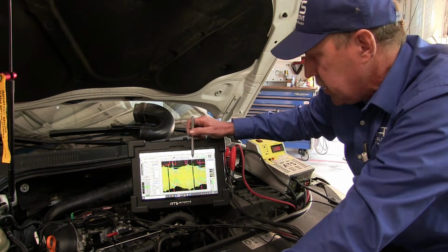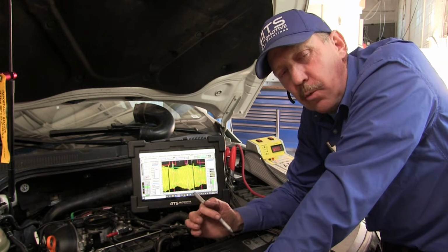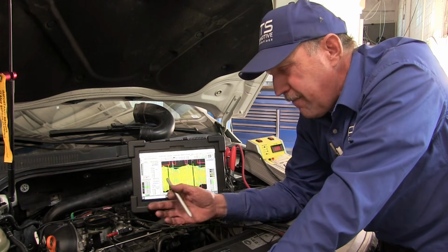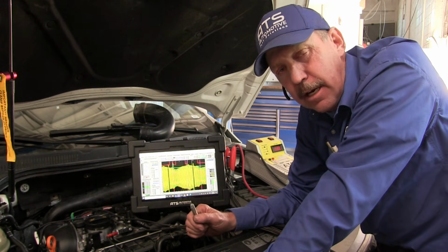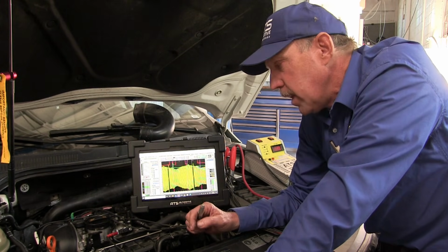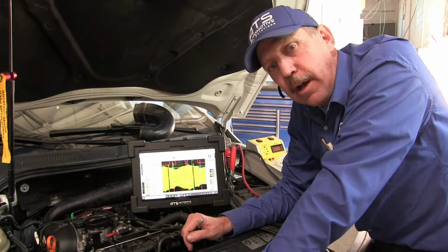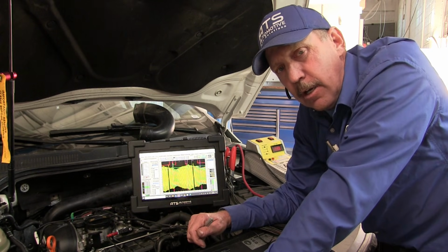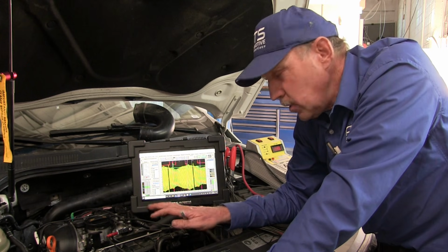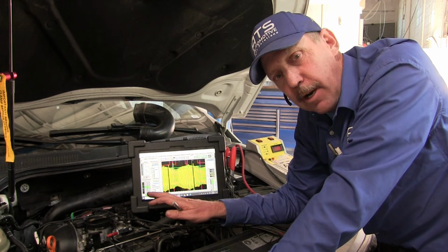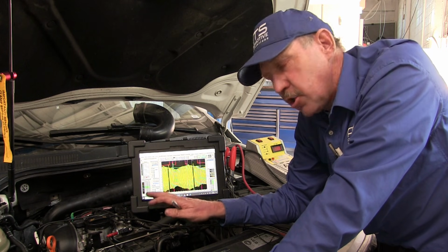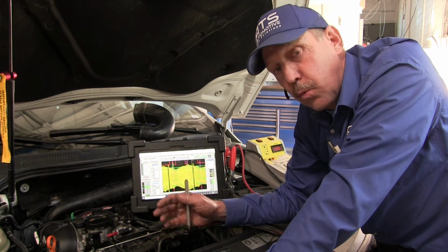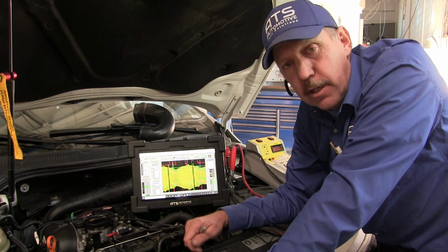So this is this far out. Now the question that we've got to ask right now is, is the crank off or is the cam off? We can't tell that by this data. So what I want to do is pull the number 1 ignition coil out and the spark plug, and we want to do an in-cylinder pressure reading so we can analyze the data. Once we can see the in-cylinder pressure, we'll know where the valves are actually opening and closing, and we can make a better determination on what's wrong with this engine. So let's go ahead and get that spark plug out.